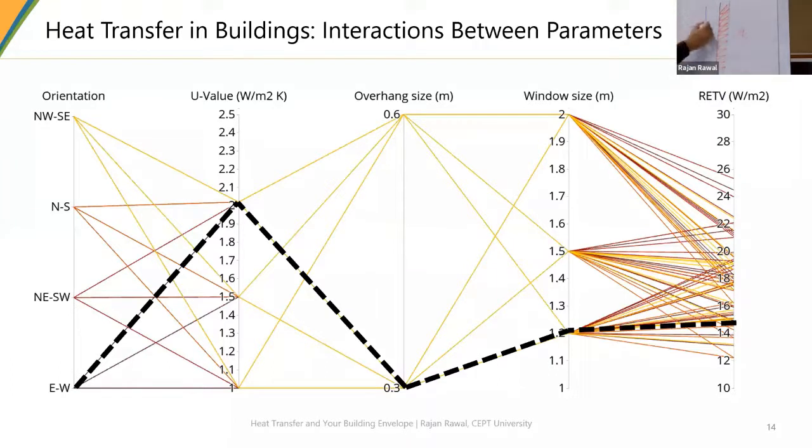And if you are bringing some kind of solar radiation, making this cavity warm, and then you are bringing that air, sorry, other way around, that air from this cavity to inside of the spaces, this warm air is likely to impact this thermal mass over a period of time. And this thermal mass may gain heat from the warm air which is moving here.